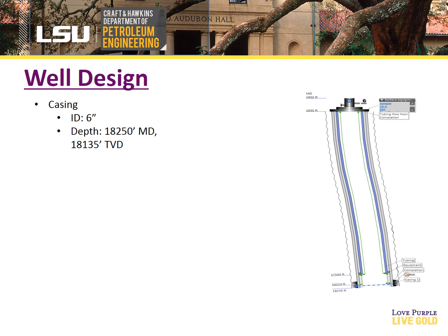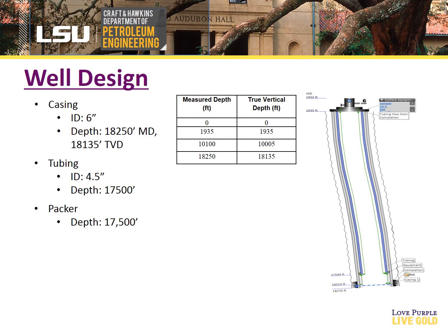To complete this component, we inserted our casing, production tubing, and packer. Following the installation of our tubulars and packer, we entered our values from the deviation survey in the Tortuga wells. Last, we implemented our open hole completions. The completion tab consists of three sub-tabs: reservoir, skin, and fluid model.